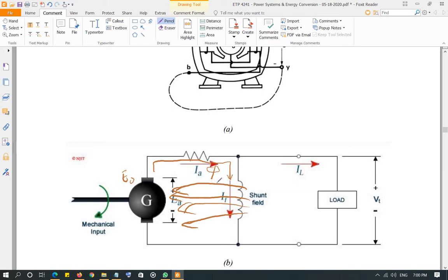Since the flux increases and is still linking with the armature, the E0 value is going to go up. Now this higher E0 value will run higher current, and that higher current will produce higher flux. This process will keep going until saturation happens, and E0 is going to be whatever the rated induced voltage is in the shunt generator. So that's how voltage is induced in the shunt generator. We don't need any external source. That's a huge advantage of the shunt generator.